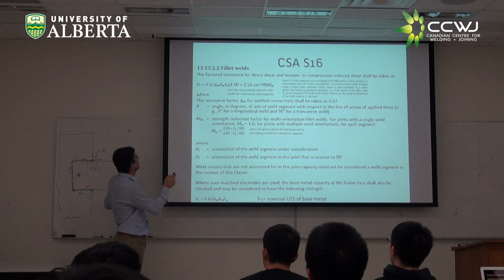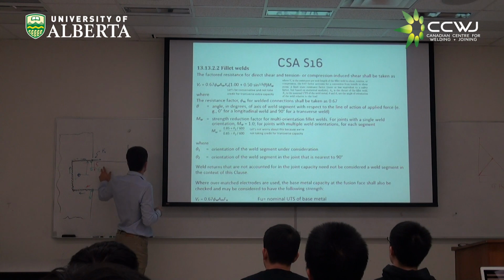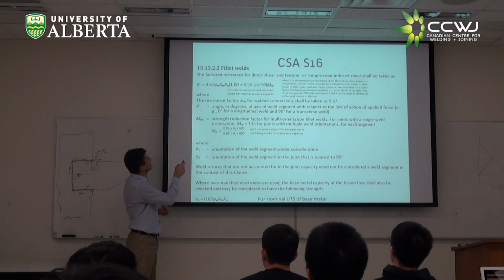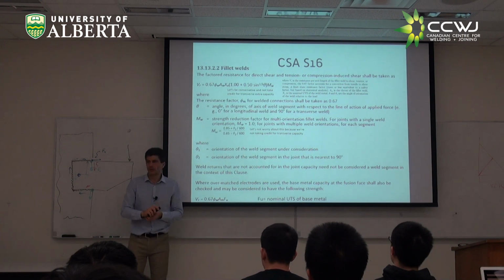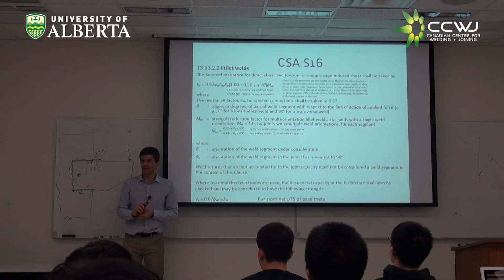And voila, you can do the same process as before, because you knew the force per unit length you needed, and now you know everything except the size of your throat. And you calculate the throat straight from there. It's pretty amazing.